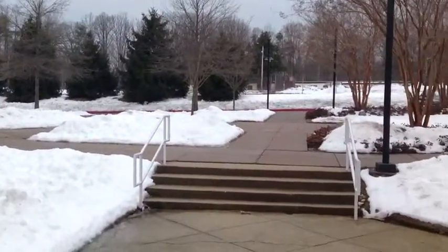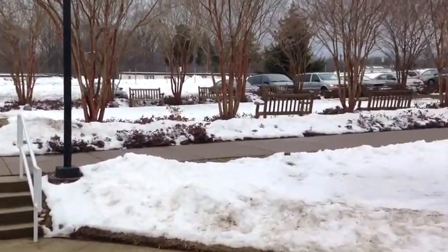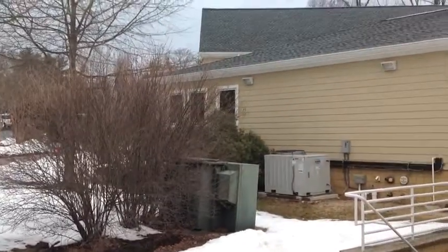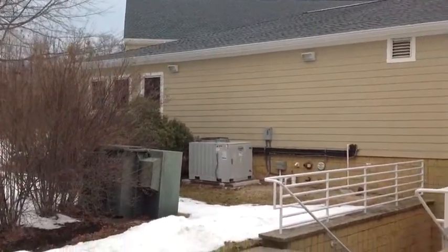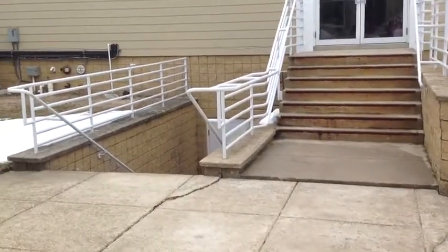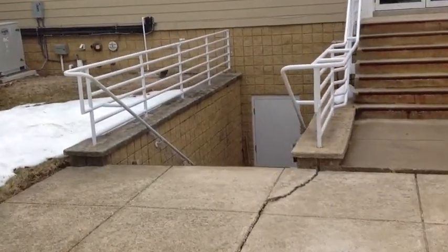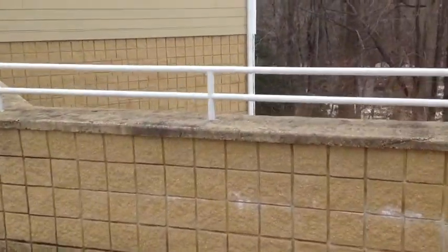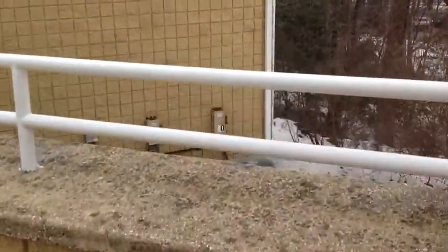As we pan around to the right, we'll go back to see the view of the admin and school building, and we will see the last of the 3 Aeon split systems. There are a total of 5 Aeon systems in the school/admin building, 3 of which are split system ERVs, 1 is a DX style rooftop, and then 1 is air handler 12 with condensing unit 12.